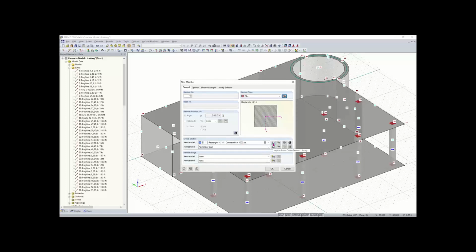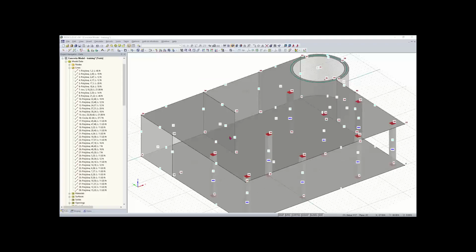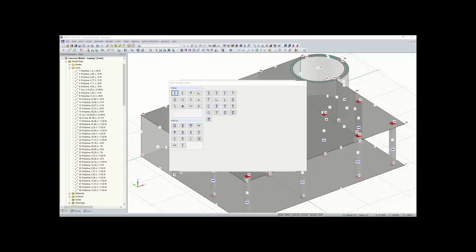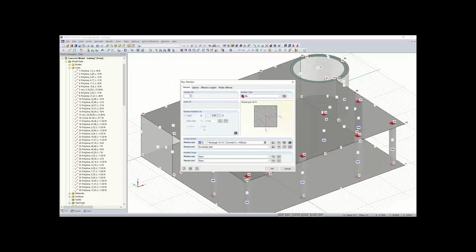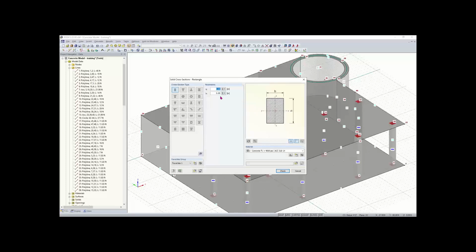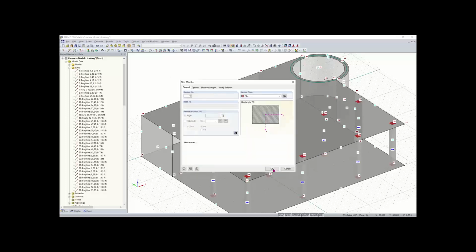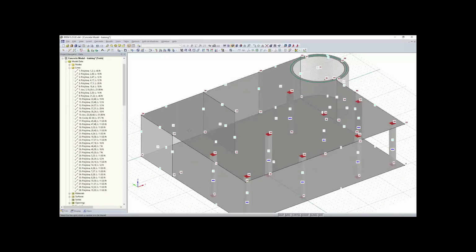And now I just need to change my cross section. And that'll load. So once I create my cross section here, it's going to be a 7 by 5 parametric massive section. So it'll be 7 inches by 5 inches, 4,000 psi concrete. We can hit this drop down and choose the latest standard. We'll click OK. And again, we'll click OK. And now we can draw.